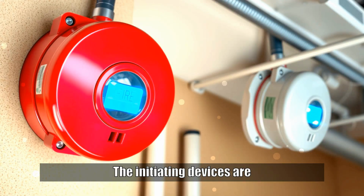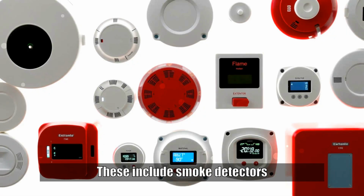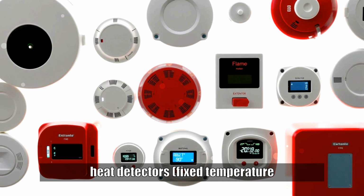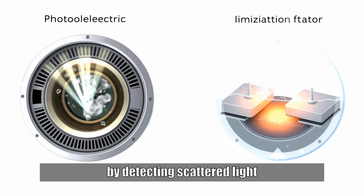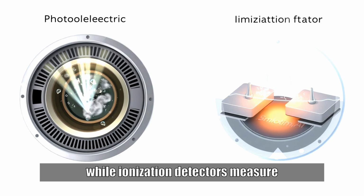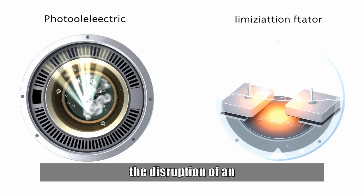The initiating devices are the sensors of the system and play the most critical role in detecting the fire. These include smoke detectors, photoelectric or ionization type, heat detectors, fixed temperature or rate of rise, flame detectors, manual pull stations, and gas detectors. Photoelectric smoke detectors function by detecting scattered light caused by smoke particles entering a sensing chamber, while ionization detectors measure the disruption of an electric current caused by smoke ions.